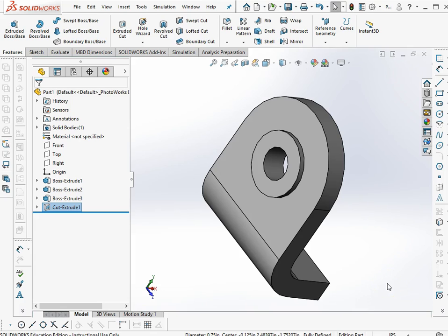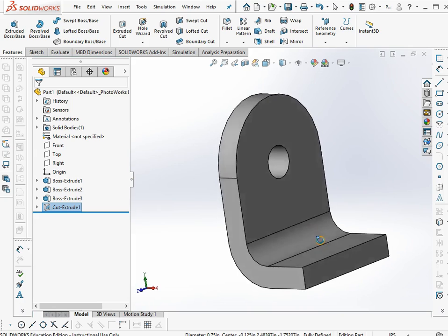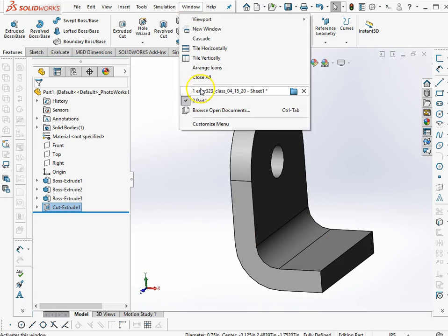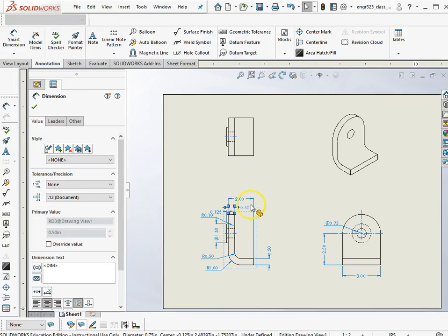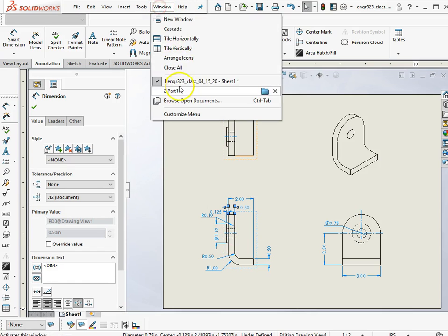Okay, the last step now I have to have in here. I think I've got everything. Let's look at the drawing again. Yeah, there is a little fillet there. That's a radius of 0.1. So there's a little fillet there that goes all the way around that boss.